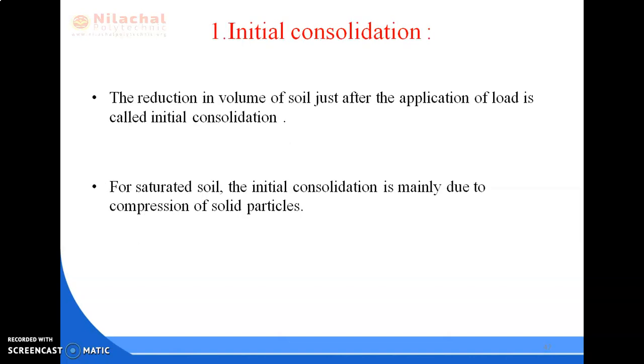So first is initial consolidation. The reduction in volume of soil just after the application of load is called initial consolidation. For saturated soil, the initial consolidation is mainly due to compression of solid particles. So this is known as initial consolidation.